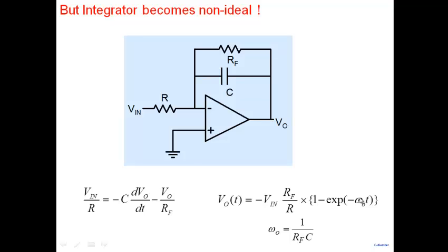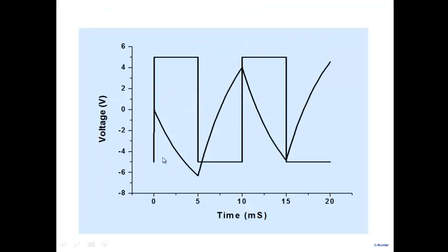And discharging also becomes exponential. So this is what I'm showing you here. If you apply, let's say, a square wave, your integrator may show a charging which goes like this here and a discharge which goes like this here. Now, what we want is an ideal integrator.